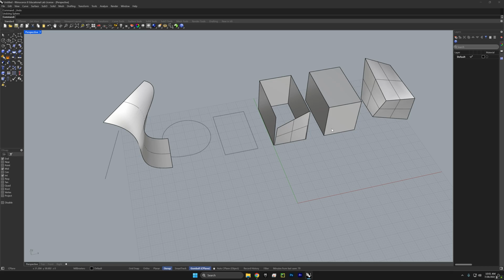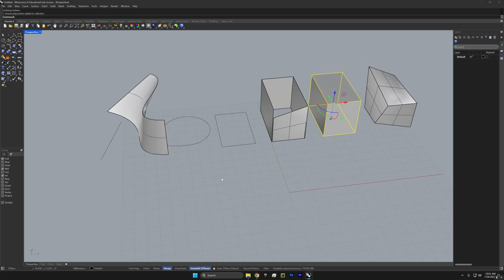Earlier, we established that we couldn't turn the control points on for this solid polysurface. There are some special circumstances where we can turn control points on for solids, though, and that is in the case of single surface solids. And so if we come up to the solid creation button on the left here, and let's go down to the lower right corner of it where it says Cascade Solid Creation and click on that. And let's actually dock this by grabbing the top of this menu button and bring it over.